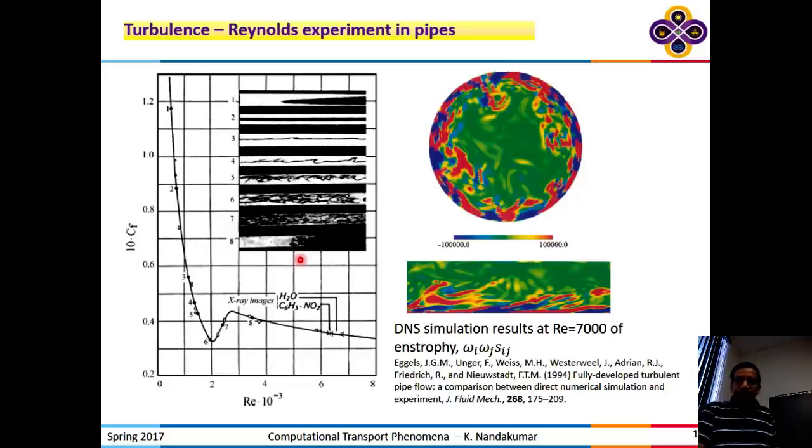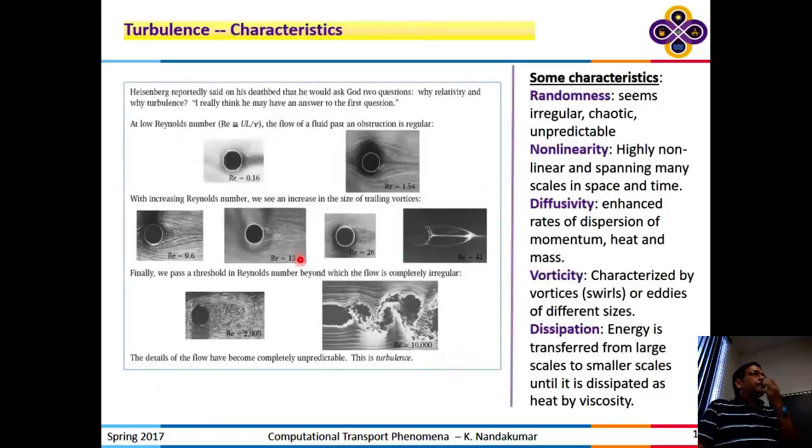So, what do we need to know? The secret about understanding turbulent flow is hidden in the Navier-Stokes equation, but because of its highly nonlinear nature, we cannot solve it analytically. But we can do it computationally if you have extremely powerful computers, because you set up the problem the same way that you do in your assignments, but you need millions of grid points and an extremely small time step size as you increase the Reynolds number.